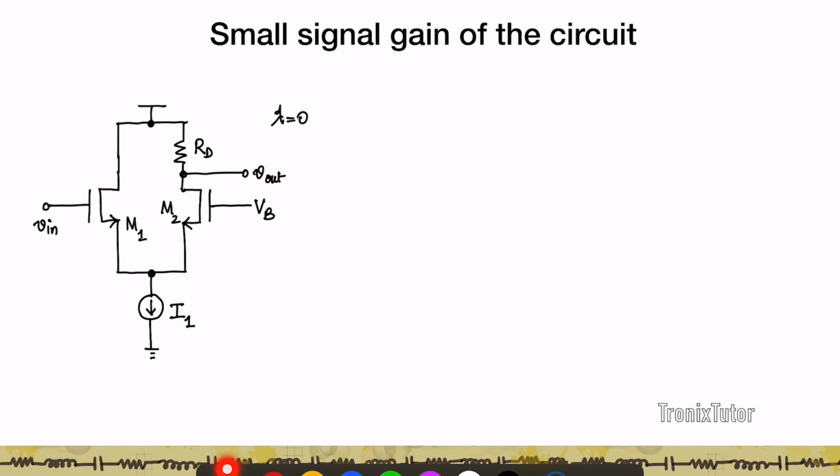Alright, now let's look at another circuit here. So again here you're asked to find the gain of this circuit. So first thing first, this circuit is slightly different from the previous cases, because while I'm giving the input to a transistor M1 here, I'm not collecting the output from any of the other nodes of M1. So this essentially tells you that this is not a single amplifier stage, but consists of more than one amplifier stage, right?